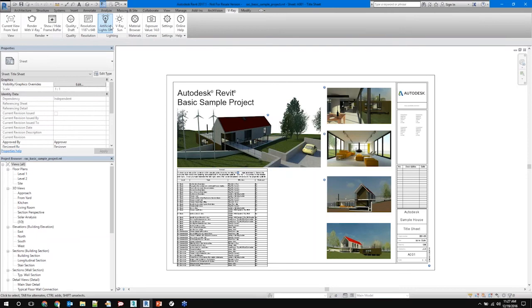This is where we'll turn our interior lights on and off, and again, all we're doing is using what's in your BIM database. So make sure that your lights are correct. And one tip, if you will: most of the light families that I've seen in Revit have an issue where the point light object itself is buried inside of the geometry. You'll want to make sure that you pull that light object down and outside of the geometry for it to show correctly.